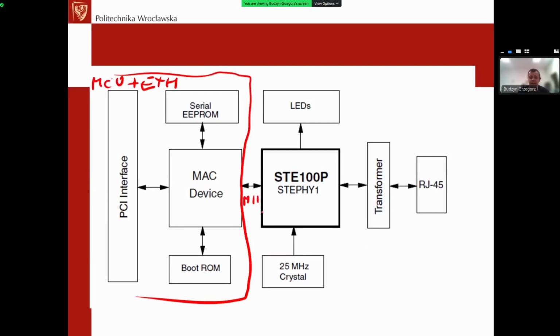and the Ethernet block delivers two types of interfaces, MII and MDIO. These are the standard interfaces for connecting the interfacing chips. And the interfacing chips theoretically should be simple to use. I tried to show you the USB interfacing chip, which today requires a power supply, a few configuration pins, and that's done. You configure it through a USB connection.